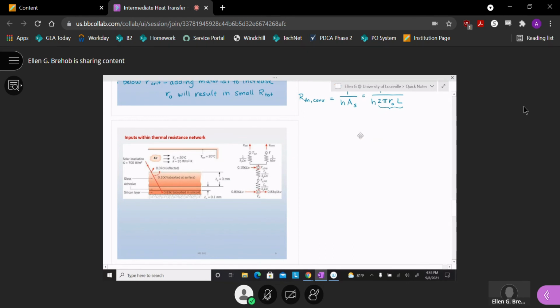In this problem, we are going to use a thermal resistance network, but we are going to handle having heat added at certain nodes in the resistance network. Let's make a note: I cannot write a thermal resistance network equation across a node where I have heat addition, but I can write a summation at that node.